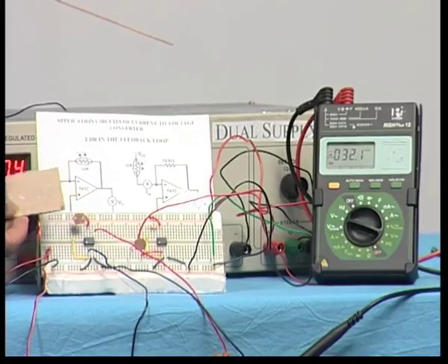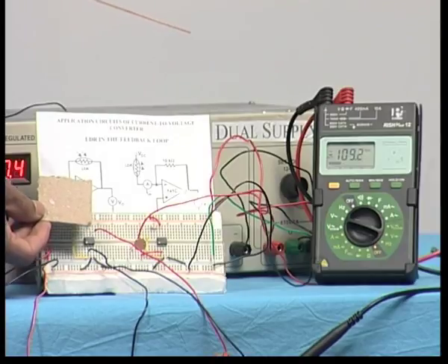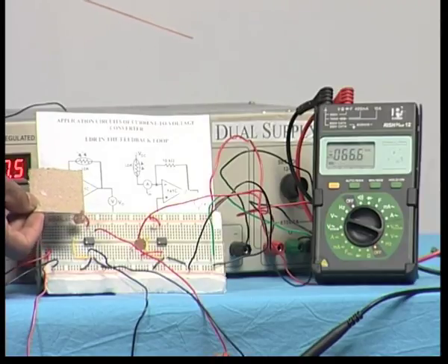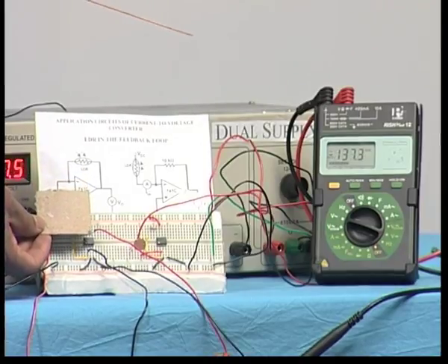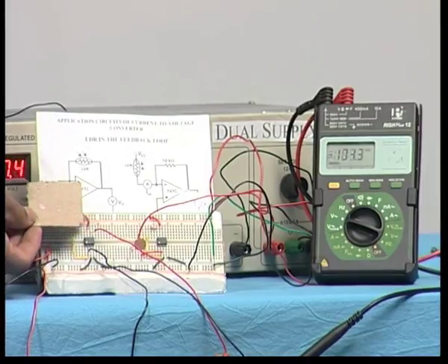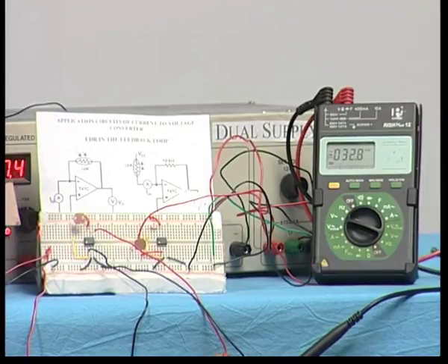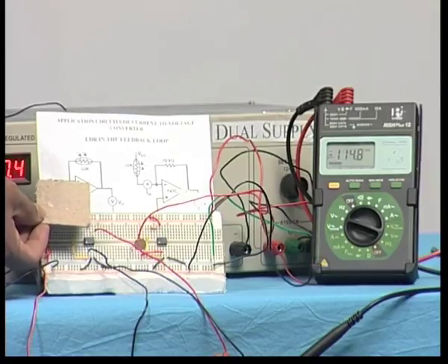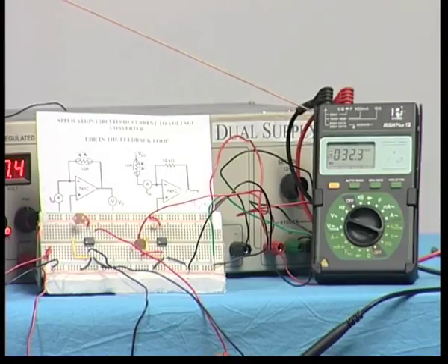This is because when the light is stopped from the LDR, the resistance of the LDR increases, we all know that. So you can see this can be used to detect light intensity. When I close the LDR, the resistance increases, the output voltage increases. When I remove the lid, then the LDR is exposed to a lot of light, and therefore the resistance is small and the voltage is also small.